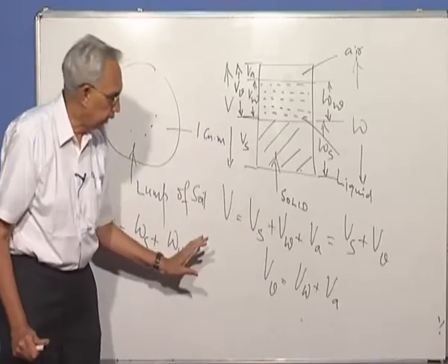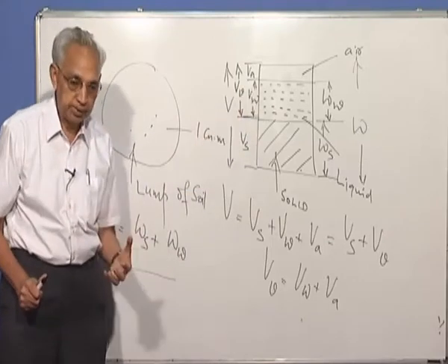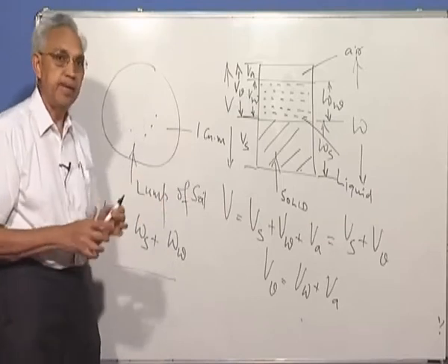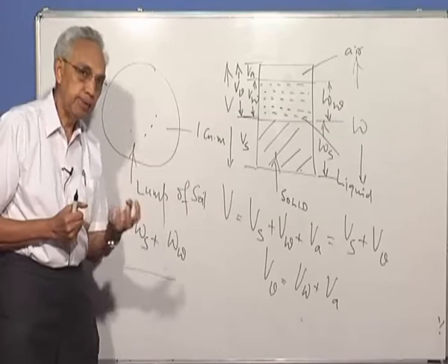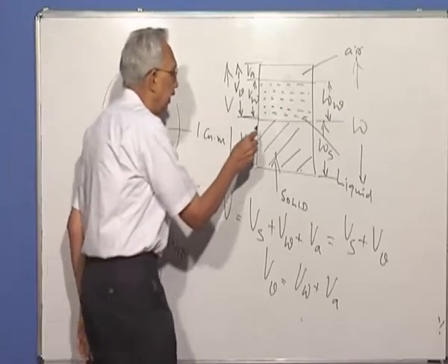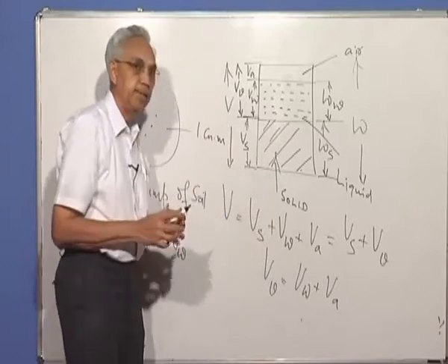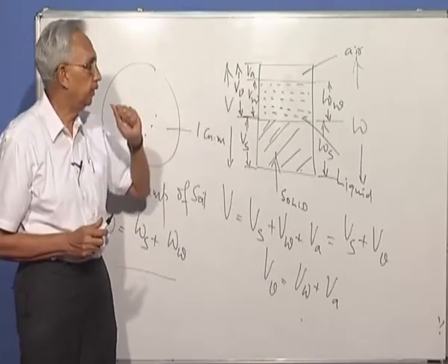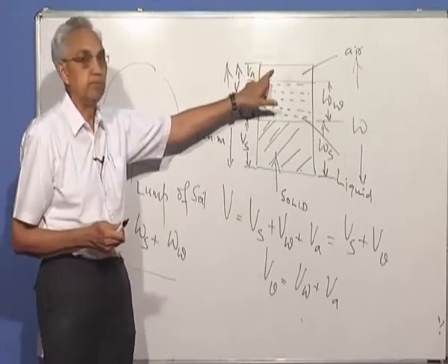Solids. Please remember that. So when we talk of different constituents and proportions, we need these parameters. Once again, I had taken a piece or lump of soil. I put all the solid grains together and found the volume of the solids, called Vs. I had taken the water in all the voids and called that the volume of water. Whatever is remaining from the total volume, we call the volume of air.